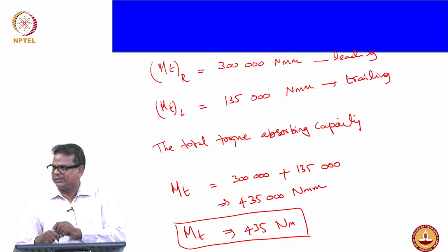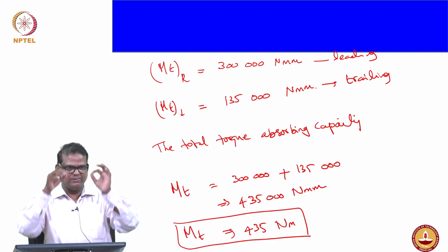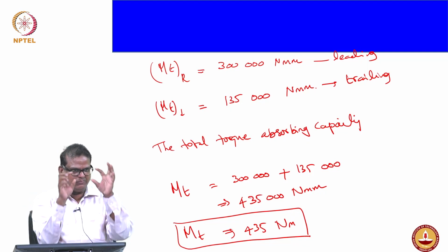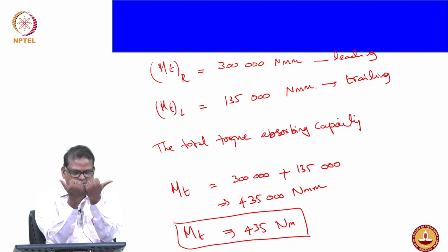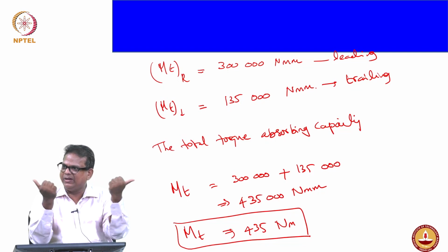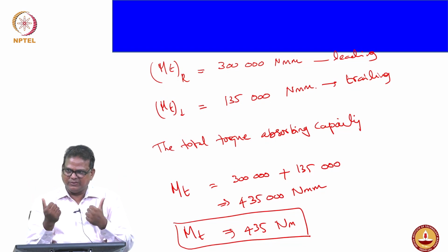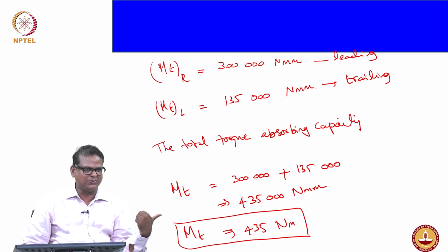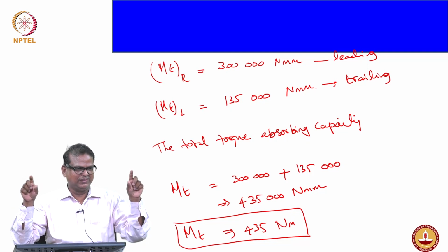Okay, is it clear now? Quite obvious, you are applying the brake through the pedal, right? The brake fluid goes through. In a drum system we have a wheel cylinder, so the pressurized brake fluid will apply activation force equally on both tips. But we know that the braking effort will be much better in the leading shoe, whereas you need to have more on the trailing shoe. That can be achieved due to the pressure variation.